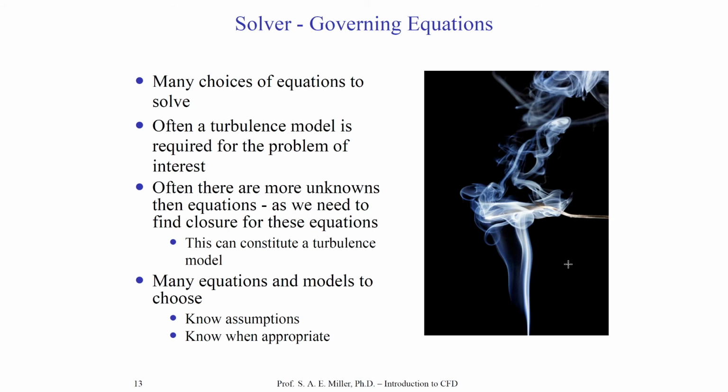a numerical solution to this problem. So what might you do? You might look at this as the computational domain, and then there's certain boundary conditions. For here, for example, up on top, I would want the smoke to leave the domain, and down here, I would want the smoke to enter the domain. The spoon itself would be a boundary condition of a wall with no slip, for instance. And maybe there's no heat transfer. We could maybe say it's adiabatic. Anyway, the smoke would come up, and it would hit the spoon and comes around and becomes turbulent.